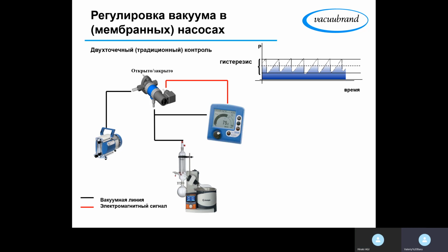So when you're choosing proper thermostatic equipment, you always need to take a look at the cooling capacity of the thermostat at the temperature that you're going to work at. I don't know if you knew about that or maybe heard about that, because this is a pretty common thing. When you're talking about -50 in the thermostat, you need to understand that you will never be able to get -50 in your reactor. In the best case, you will have -35 in your reactor because you will always need a delta T.